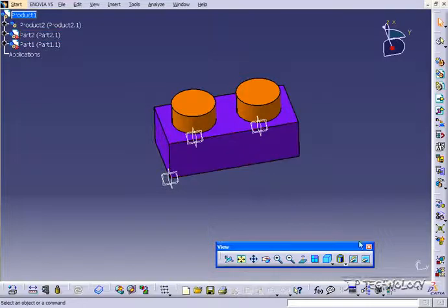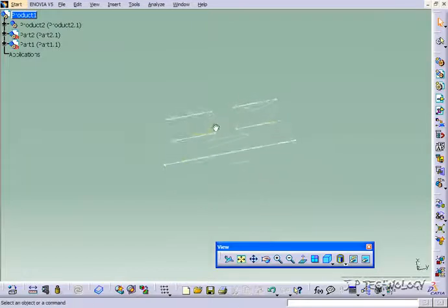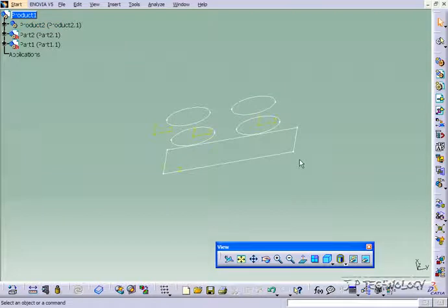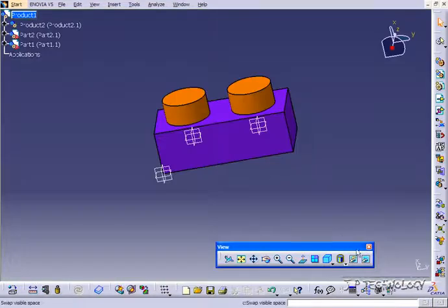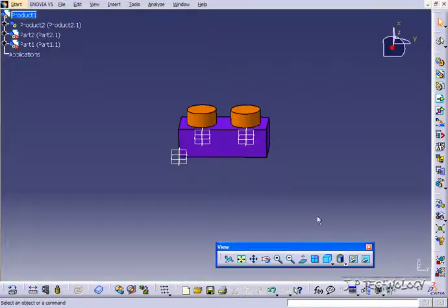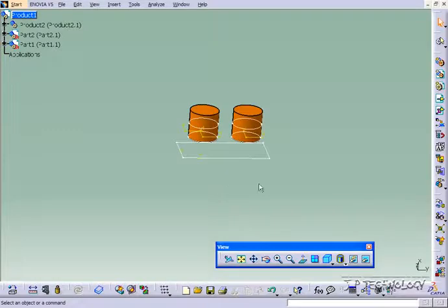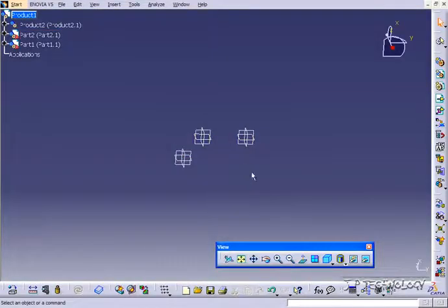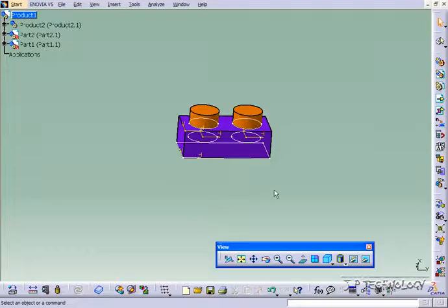And where that is in the other space. So if you click swap visible space, you get another space that shows what is not shown to your face in the other space. So everything that is hidden, so you might find sketches, work planes, and whatnot, and it'll also be the parts. So right now, let's hide this part, and if we go back, now they're in this space here. So we can hide the entire part, and it'll be in our other visible space. So swapping between the two allows you to see what's been hidden and what's been shown.